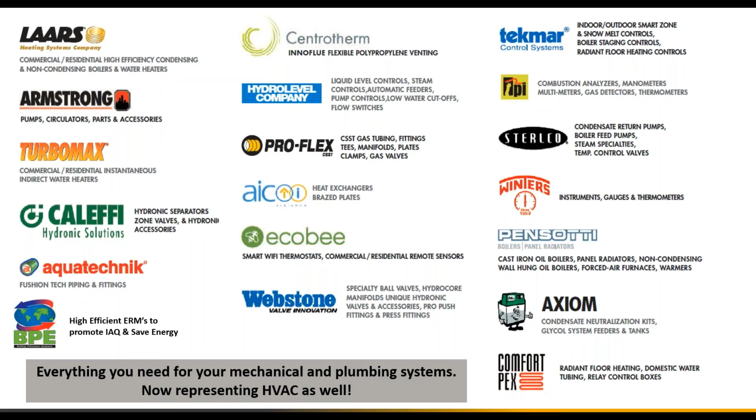So look at those types of things. Of course, an existing non-condensing boiler cannot run cold water temperature back to the boiler. Look at how old the building is, look at the radiation, make sure it's fully accessible, and then verify for yourself how one can go from a 20-degree to a 30-degree delta T, or maybe a 40-degree delta T, so that you can really drive down that return temperature.